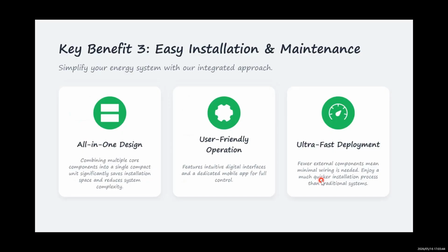The third benefit: because the hybrid inverter is a compact solution integrating the MPPT, the PCS, and the local controller or EMS software functions, it is very easy for installation, maintenance, and deployment. It's an all-in-one design combining multiple core components. It saves installation space and reduces the system footprint.